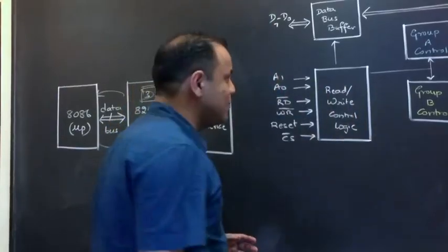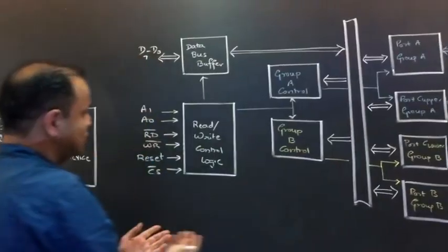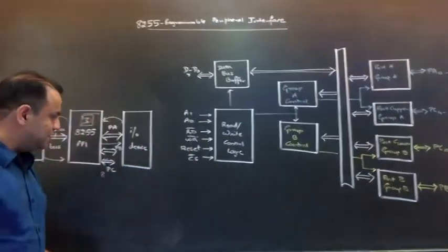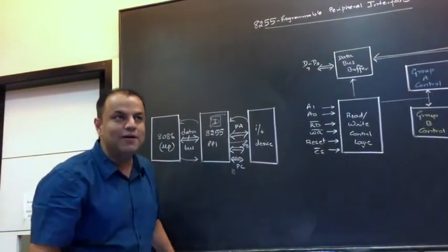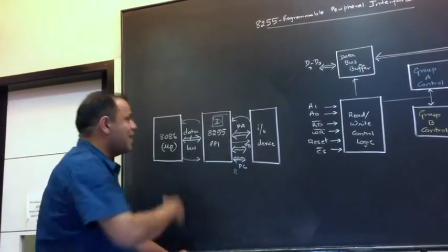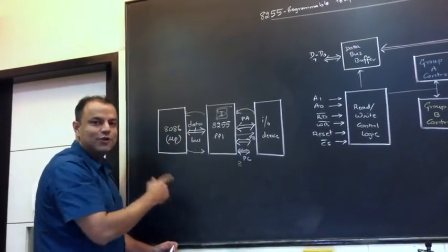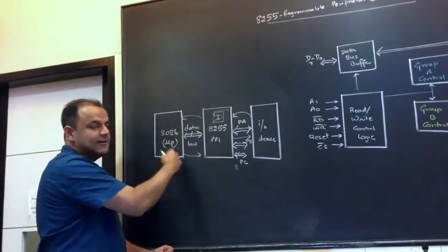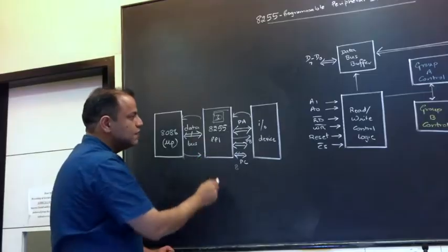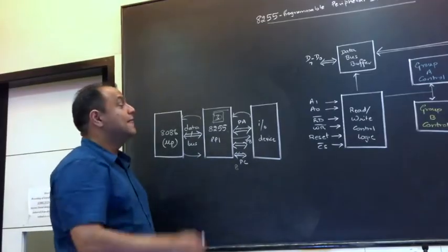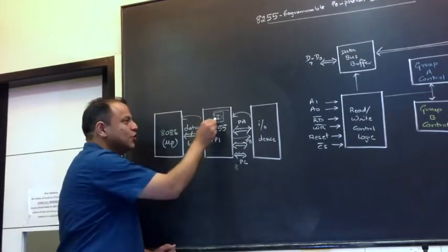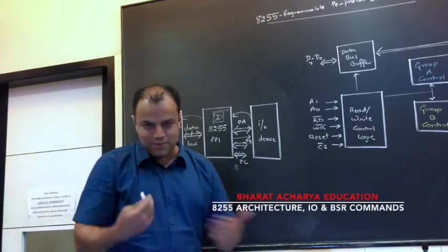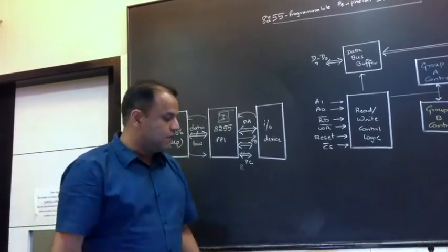In 8255, look here. In the whole architecture of 8255, there is no clock. That means 8255 doesn't understand time. That means it doesn't care how long the processor takes to get the data. Till the time the processor asks for the data and takes the data, 8255 will not give permission for the next data. That means no matter what happens, you will not lose the number 3. And 3 is just symbolic. That means any data transferred in the system will not be lost.